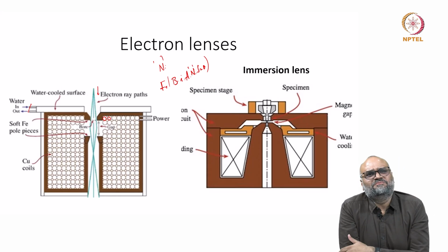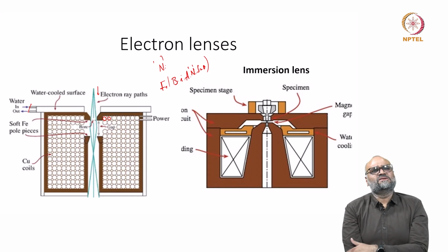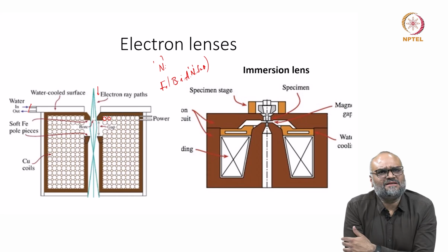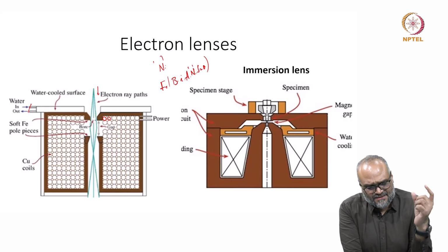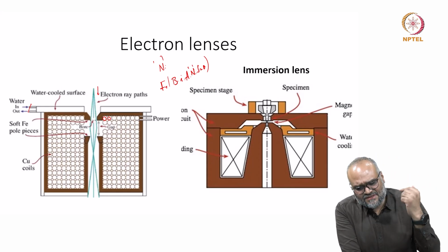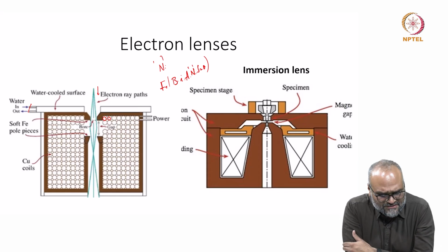Also, I was mentioning, if the chilling of the electromagnetic lenses or the chiller stops, the entire microscope also shuts down. It's a big problem. So you need to bear in mind that the chilled water supply is important to cool the lens from outside. So you're circulating cooled water to extract the heat that is produced from this and to maintain the entire column of the microscope at a uniform temperature.